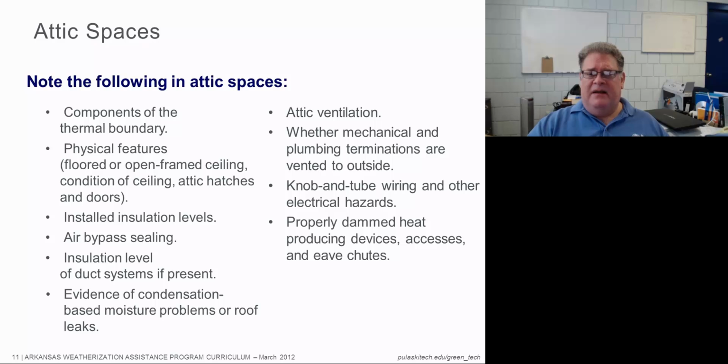Okay. How about knob and tube wiring or other electrical hazards like uncovered J-boxes or splices that are not in J-boxes that are covered? So junction boxes are required by the NEC, and they also have to be flagged if we're going to cover them. They must remain accessible. By flagging, we make them accessible by identifying their location.